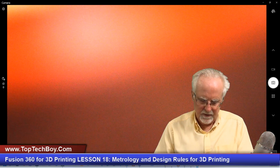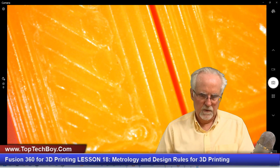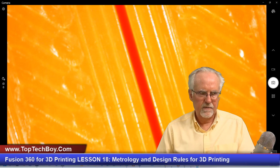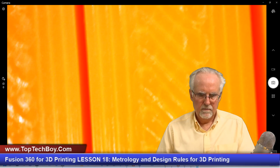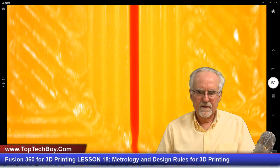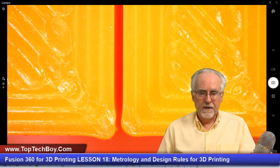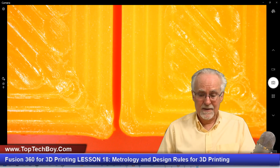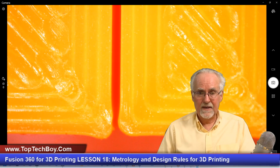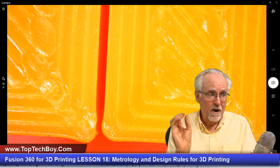Okay, and now let's come in and look at this line that we had defined. This is the 0.2 millimeter line, the dark orange. If you look down here, you can see at the corners there still is an open gap, but it is closed up. The gap is no longer 0.2 millimeters. It looks like the gap is coming down to about 0.1 millimeters. So my gap is choking off at the corners.